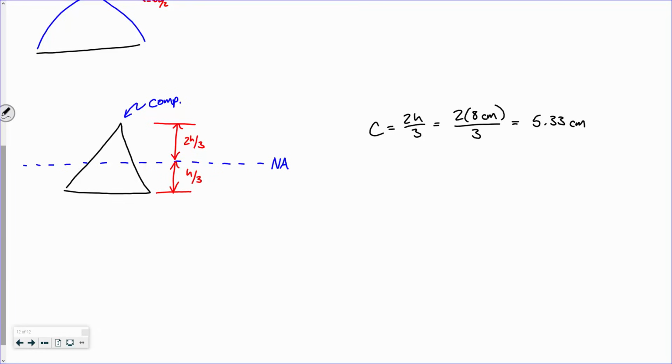Excuse me. Now, we're going to need the moment of inertia. So, okay, that comes from right here. All right, remember our bending stress formula? We measure from the centroid to our extreme fiber. You remember that? Okay. All right. Ultimately, what we've got is a bending stress profile that looks something like this.